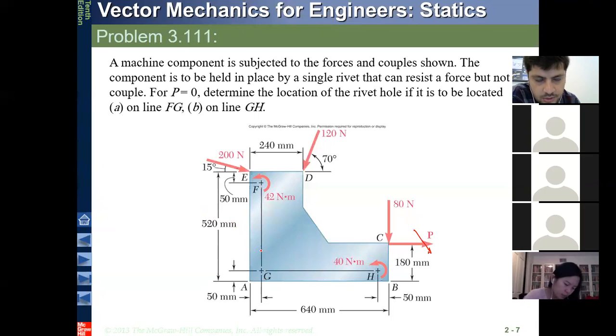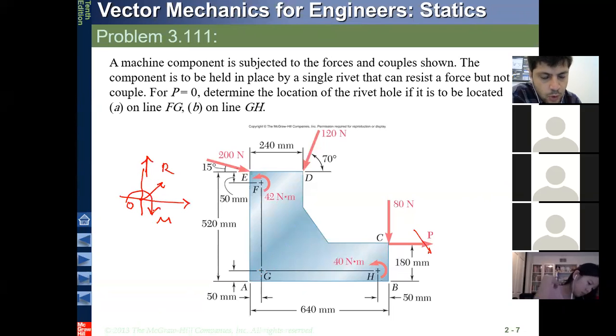So it is obvious that you first need to calculate the resultant in X and Y direction, and then you can take any point in the system and calculate the moment around that point. And when you calculate that moment, this is the resultant force, and also you have a moment. So you need to find a location for a point that there's no moment.